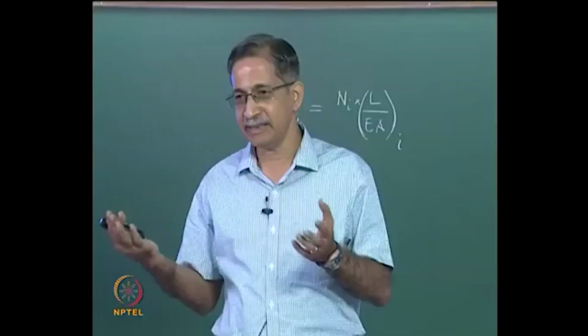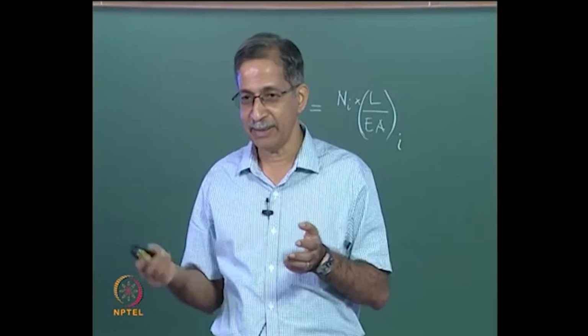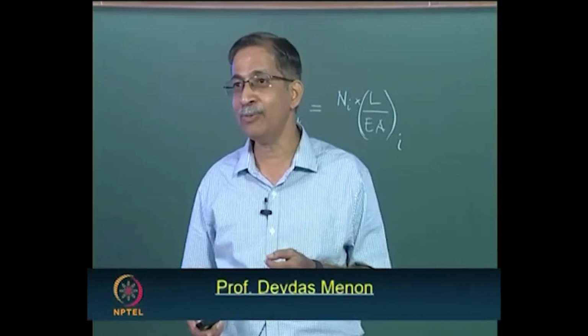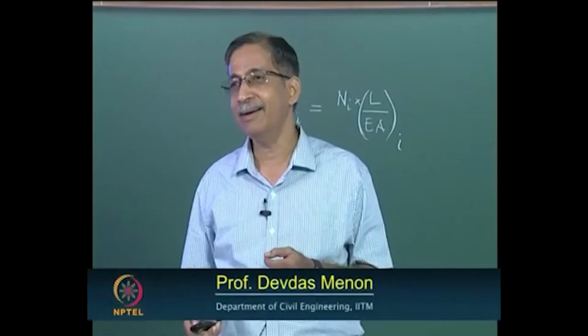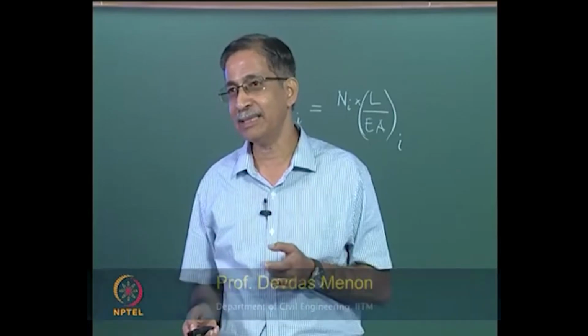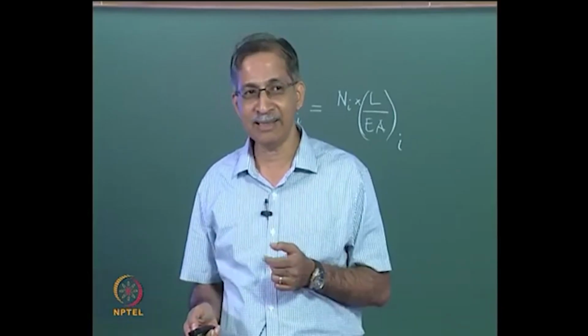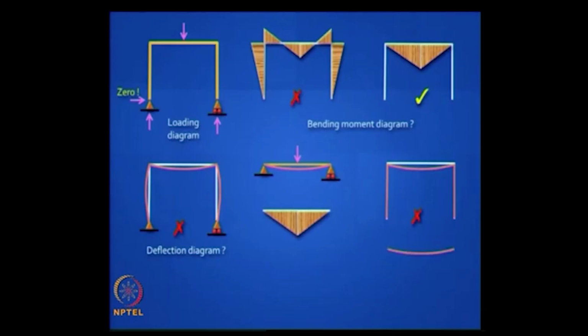Because the curvatures are the same, the bending moment diagram is the same. Then what should you do for the vertical elements? Yeah. You preserve that. So this is wrong, because this would be violating the 90 degrees. So you have to draw like this, which is still feasible because the roller support allows a movement. So if your original shape was this, a student who can answer this completely is a rare student.